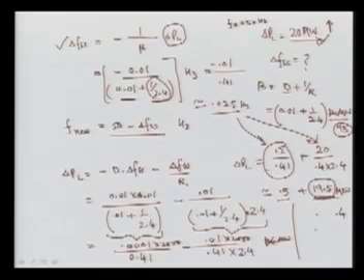So this is your steady state response, and the static response of this ALFC, that is the area load frequency control loop, yields important information about the frequency accuracy, meaning how much you are getting in the steady state. However, the dynamic response of the loop will inform about the tracking ability and the stability of the loop.